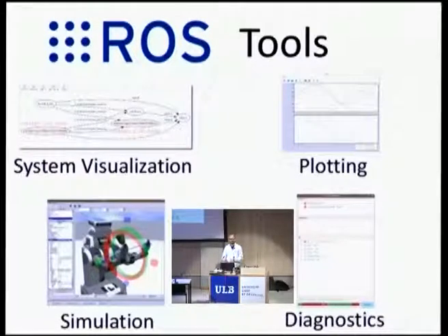You can essentially dump that message bag upside down and shake it at the right frequency so all the messages dribble out. The rest of the system has no idea what just happened. Anything downstream of the actual producers of those messages doesn't change anything. It just looks like the same system was happening. It doesn't realize that it's essentially a time warp to last week, or whenever the bag file was recorded.